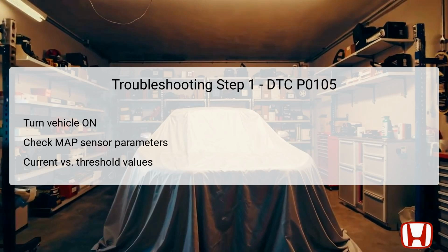If the current reading matches this threshold, it confirms that the fault has been effectively duplicated, allowing you to proceed to Step 3. However, if it does not match, you should move on to Step 2 to further investigate possible issues with the system, such as intermittent failures or wiring problems. This step ensures that any subsequent diagnosis is based on accurate initial readings.